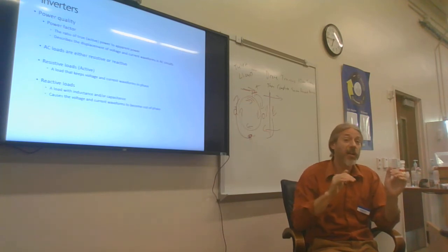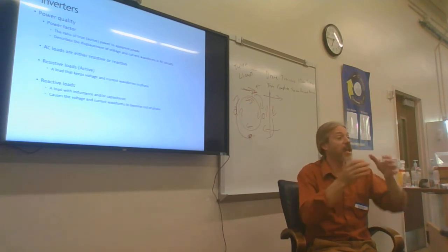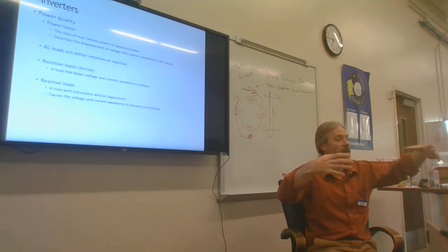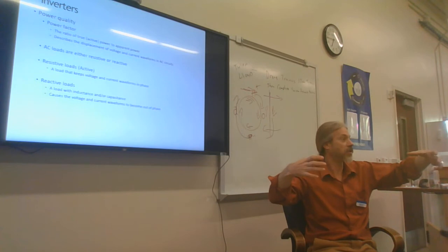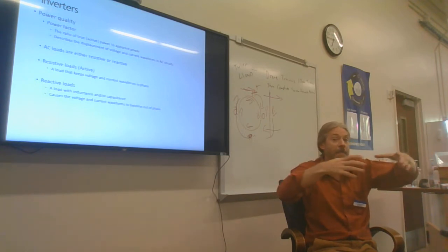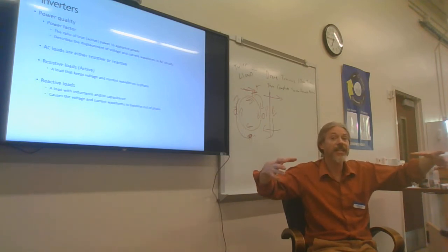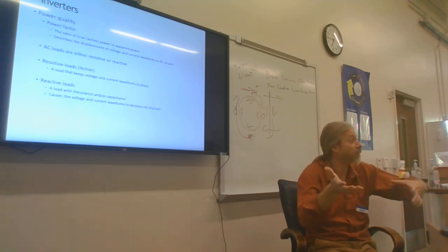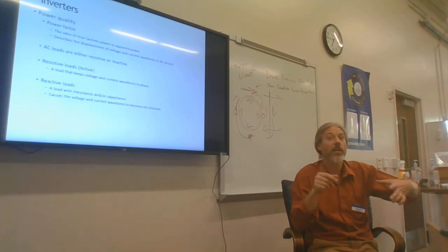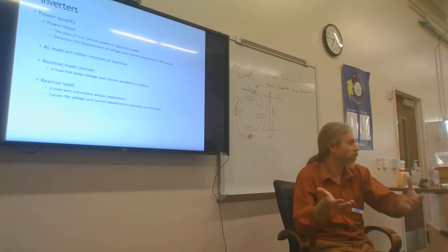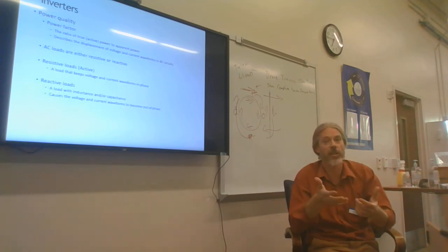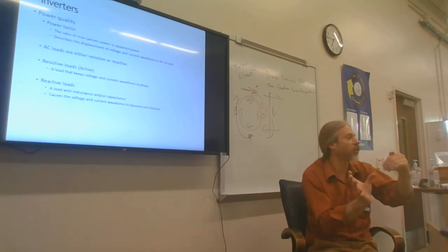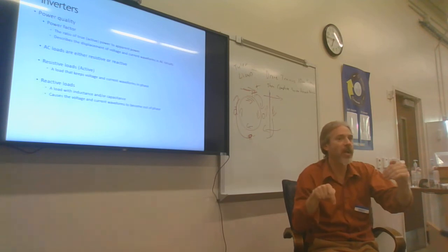So as that current begins to increase, then I begin to create a magnetic field around the conductors where the current is flowing. That magnetic field being created is affecting either other magnets or other magnetic fields within this inductive load. That induction is delayed. It doesn't match the cycle of the AC waveform.